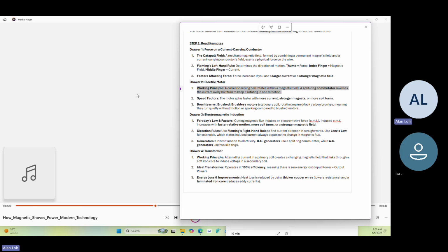Okay, that establishes how pushing a current through a magnetic field creates motion. But the conservation of energy demands a two-way street, right? Yeah, meaning if you manually force a wire through a magnetic field, the field pushes back on the electrons themselves, inducing a voltage, which is electromagnetic induction. Good old Faraday's law. But the critical piece mechanically here is Lenz's law, isn't it? It is. The moment you induce that current, it generates its own magnetic field, and that new field always flows in a direction that directly opposes the physical motion that created it.